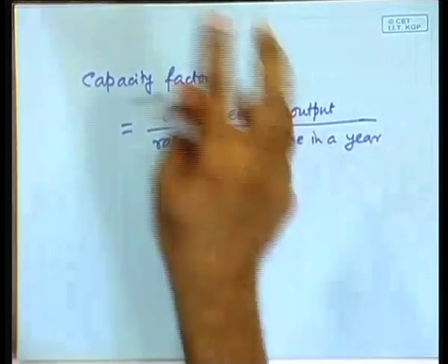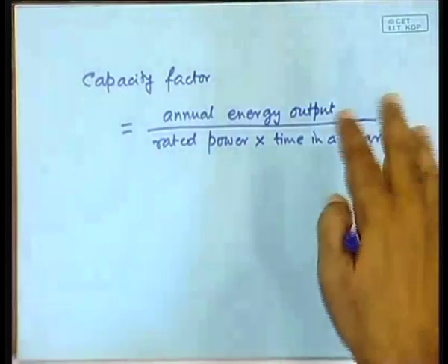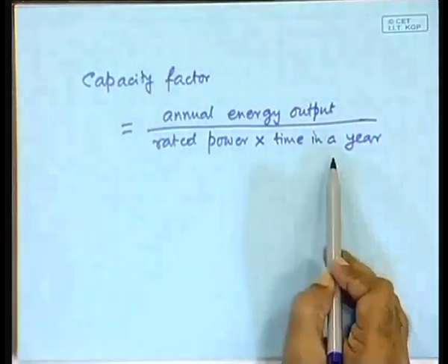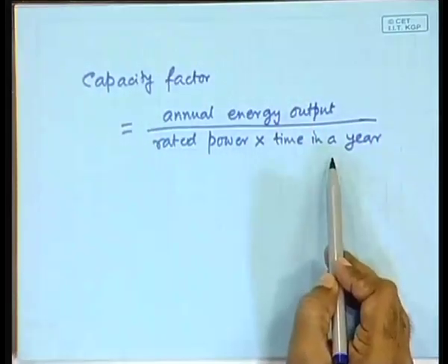and that is exactly why the statistical distribution of wind speed in that particular site is very important. You would immediately realize that different large and small wind turbines will have different capacity factors, and the one that gives the maximum capacity factor for a particular site is the right choice of wind turbine for that site.